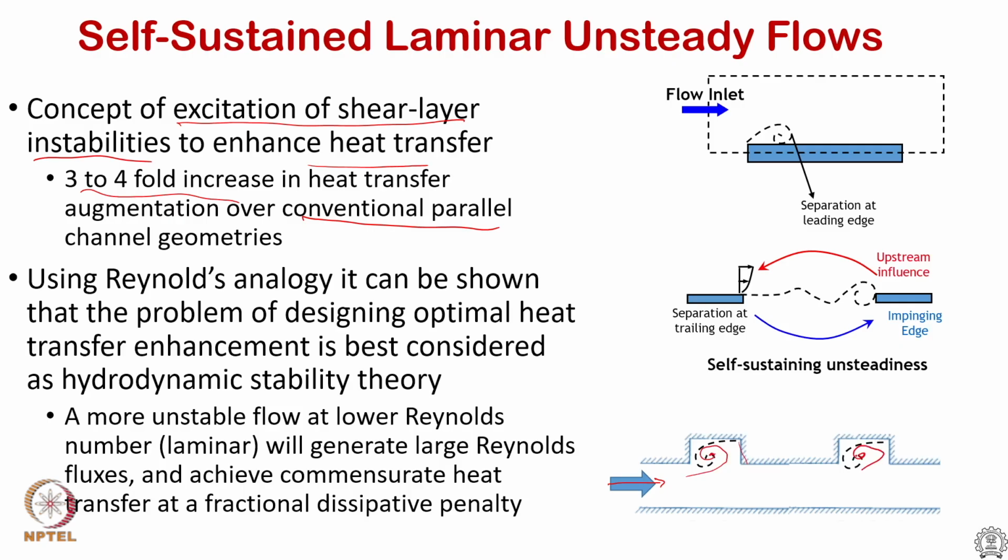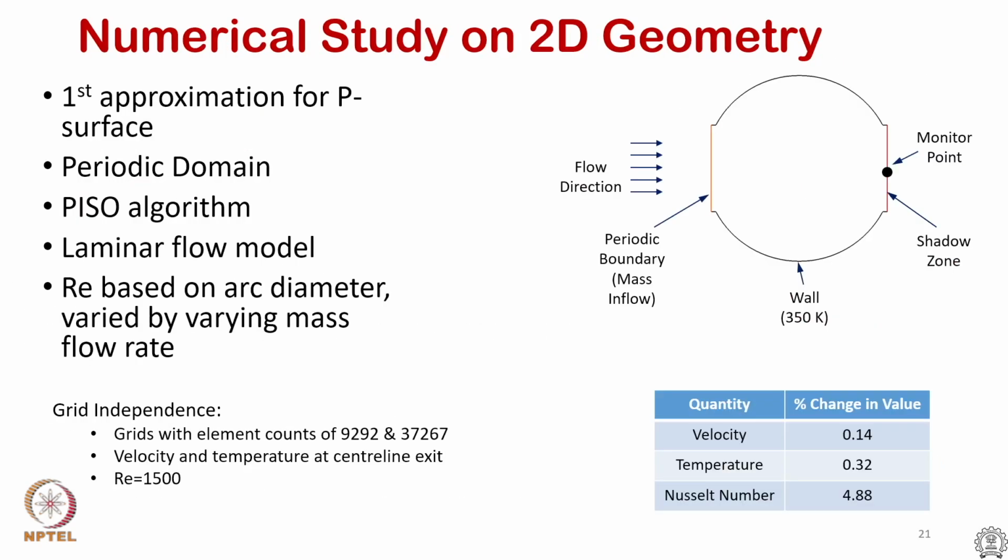and it recirculates. When the flow velocity or the mass flow rate is increased, what happens is there is a shearing layer here. There is a shear and you start to shed vortices into this stream. At lower velocities, these vortices are shed, but they dissipate very quickly. At higher velocities, this vortex shedding creates intense action, essentially unsteadiness. So as you will see in the upcoming slides, you will get some idea.